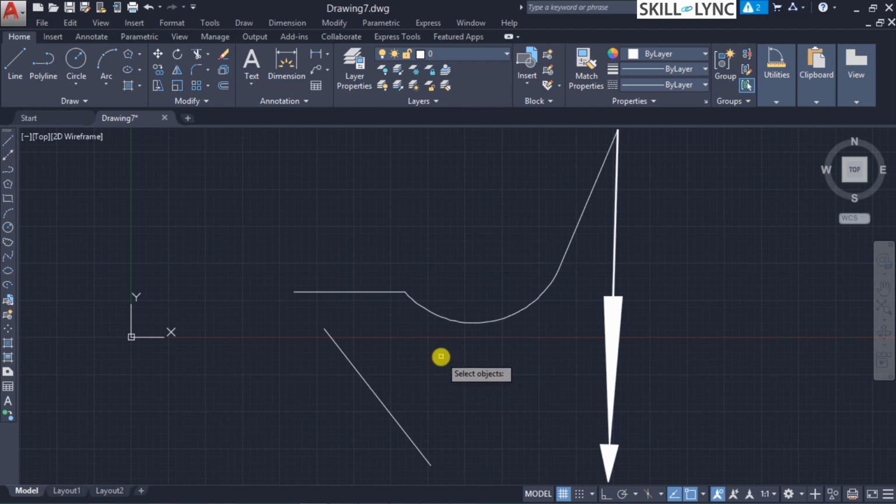So once you do, because originally what you want to do is you have to join two objects together. So even when executing the PEDIT command, you have to make sure that you have selected the objects of importance to us. So that's why you have to opt for multiple objects and then go about. So now you go on, select the two objects of interest and click enter.